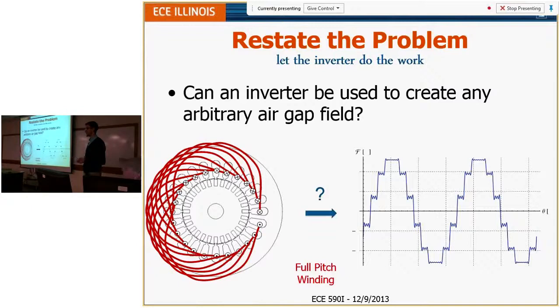Have you actually looked at what speed range, what kind of pole count would give you maximum torque over a wide speed range? No. It's something I'll do once I get a simulation working. Also the flux dynamics while switching between pole count. Yeah, I think that's going to be pretty challenging. People in the past have done their PhDs on switching between 2-pole and 4-pole, 2-pole and 6-pole, but it's all mechanical.